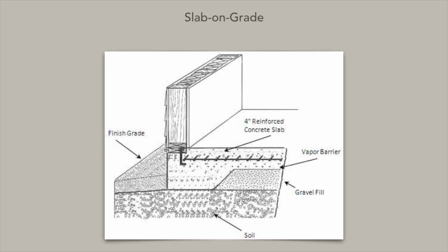This system of building a foundation is normally used for self-supporting, standalone buildings that are usually 1 story in height, such as a house, a freestanding garage, or even a large shed. This slab on grade is not below the frost line. Another common term used to describe this type of foundation is a floating slab or an Alaskan slab.